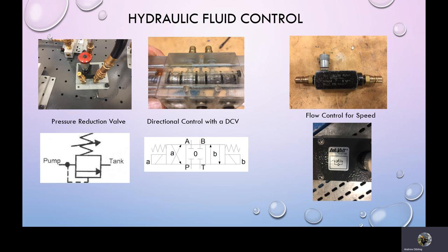and it's a closed center position. So of course, those particular actuators, linear or now, I wouldn't use this particular one on a rotary actuator because that motor would come to a dead stop as soon as I hit the stop switch. And that can be very hard on the motor. I want it to coast to a stop, which would be better. So I would use a regen center or an open center for some kind of a rotary actuator. A linear actuator for like a front end loader or excavator would be the closed center type that we have here.